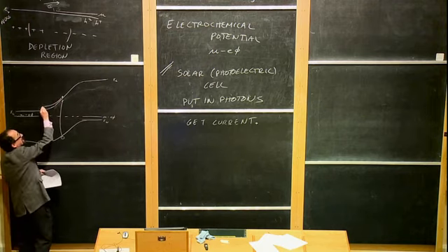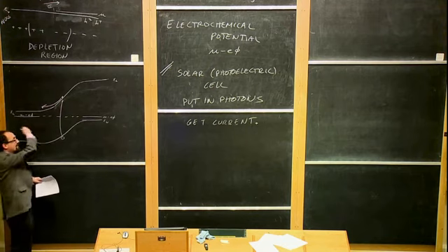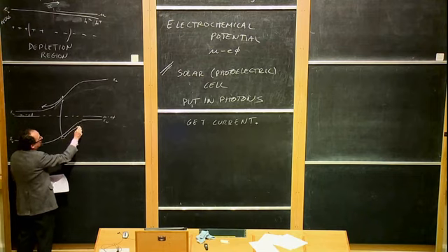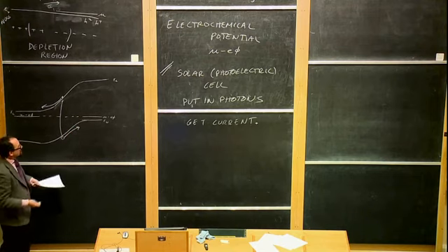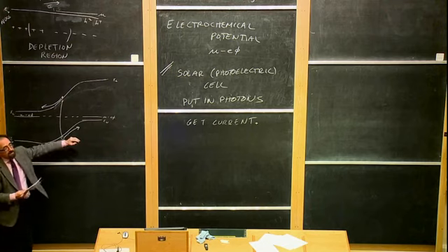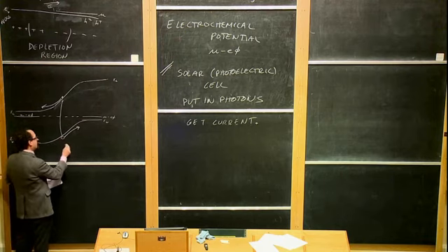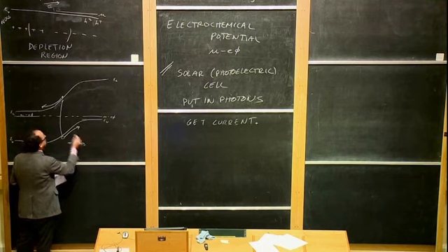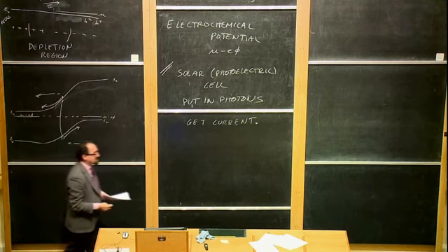And what happens is the electron is pushed by the electric field in this direction because it wants to go down to lower energy, and the hole is pushed in this direction, wants to go up to higher energy, because holes always try to go up in the band structure. And either way, this is always current going to the right. It's either positive charge going to the right, or negative charge going to the left, and both of those are current in the same direction.